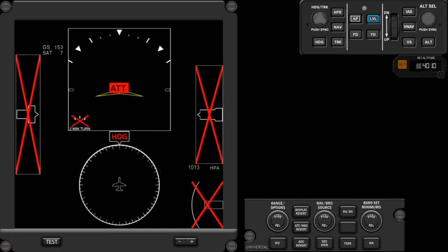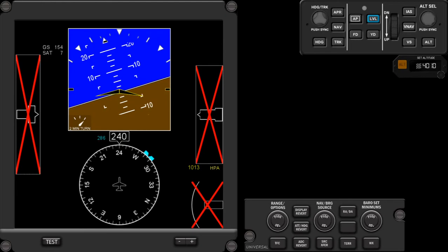So let's turn on the display now by the switch and explain. So here's the display. As you can see, we have no altitude information, no vertical speed, no airspeed, no compass, as the air data computer and the attitude heading reference systems are turned off. So I will now power up the attitude heading reference system, AHRS, which is running now.